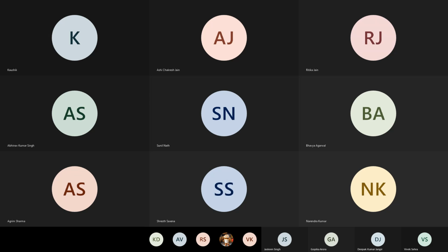Then you cool these reactants, which is delta H naught R: the integral of n Cp dT from 533 Kelvin to 298.